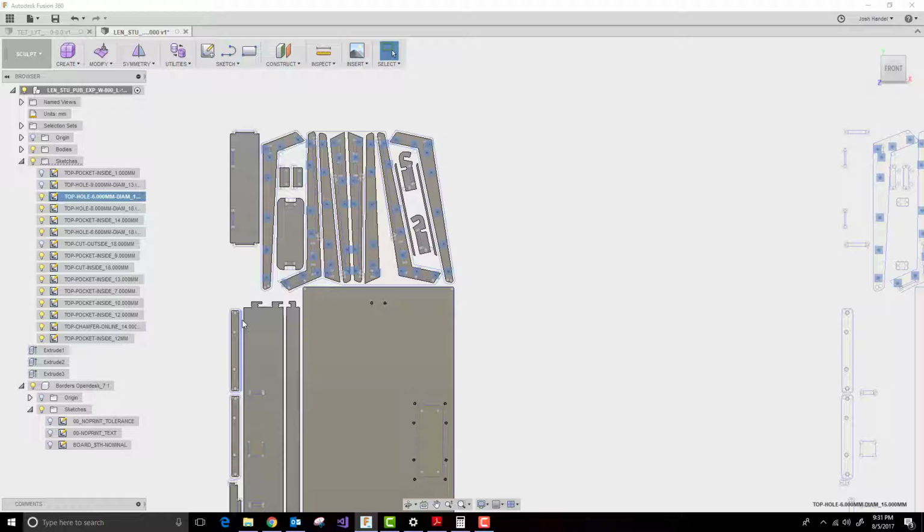But with these 6mm holes, you'll see there's a bunch of them here. And what I have found is these are, at least on all the designs I've worked with and looked through, for dowel pins to glue stuff together, to register it and then glue stuff together. So for those of you in the States like me, don't worry about getting a 6mm bit. Do a drill operation with your 1/4" bit and go get 1/4" dowel pins, whatever, inserts. That's what you're going to use.